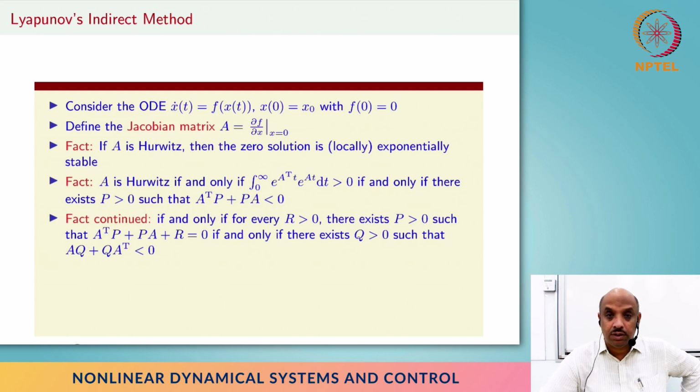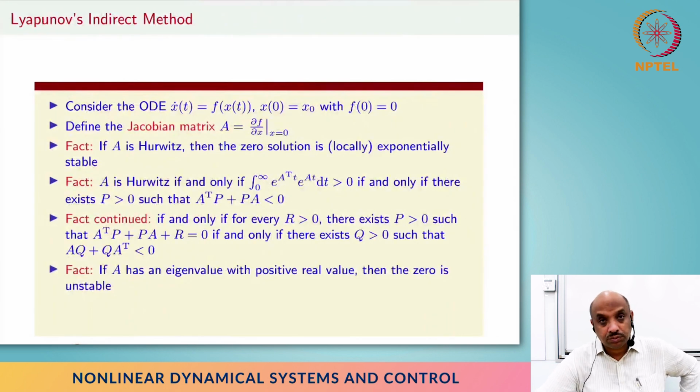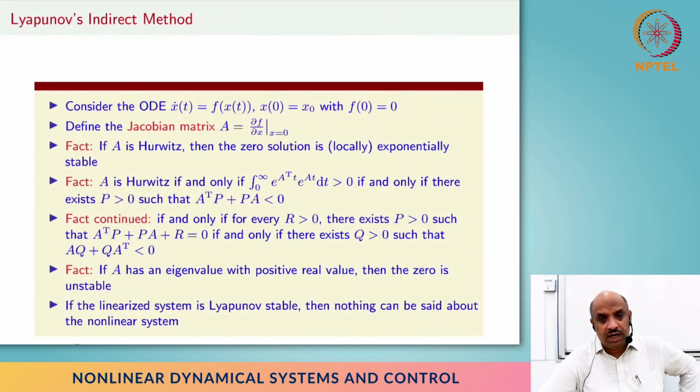And there are other inequalities, right? Today I would recommend using this set of inequalities, quite easy to do in MATLAB, for example, using something called the LMI toolbox, and one can check feasibility for these linear matrix inequalities, or LMIs, right? So in that sense, we have an ability to show stability or exponential stability of a nonlinear system through linearization and simply checking on the computer. It's a nice way of doing it. One can check the eigenvalues of A, but the fact that we have these alternative methods of checking the LMIs is powerful in a separate way. We'll look at that at a later point.